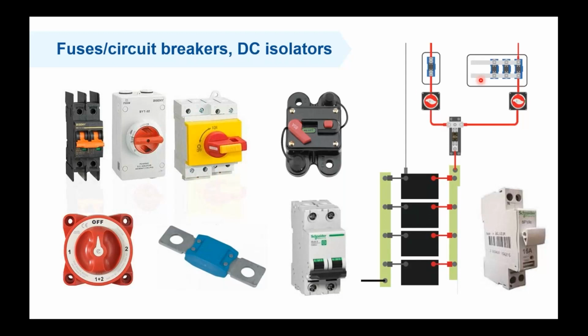So what I normally prefer in design when it comes to sizing is that I might use a cable with higher capacity. As I told you, if I have options for thicker cables, it's always good to use them. But I strictly adjust the fuse current rating a little bit higher, maybe let's say 1.5 times the maximum current of my system.